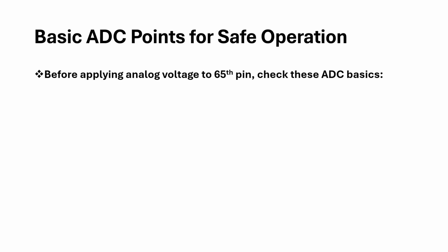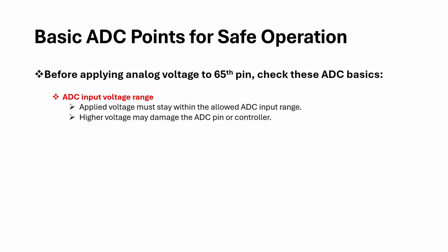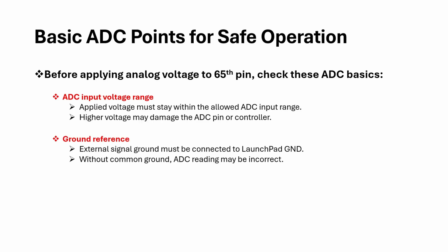for safe operation. The first important point is the ADC input voltage range. The voltage applied to the ADC pin must always be within the allowed ADC input range of the controller. If we apply a voltage higher than the allowed limit, the ADC pin or the controller may get damaged. The second important point is the ground reference. The external analog signal must be applied with respect to the LaunchPad ground. Without a common ground reference, the ADC reading may be incorrect.